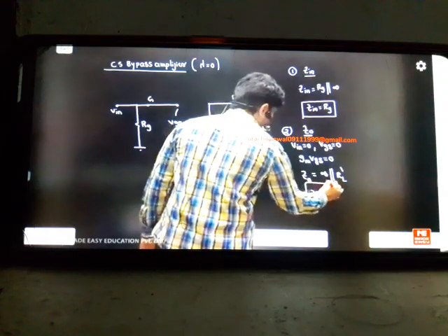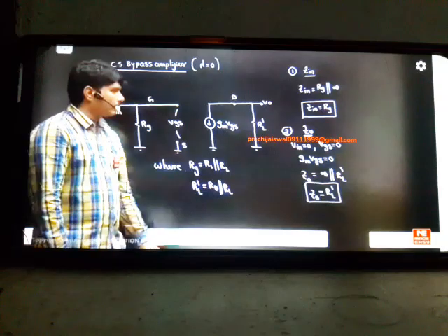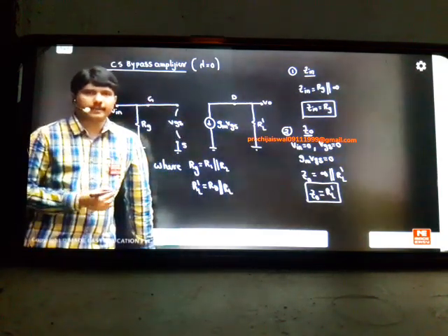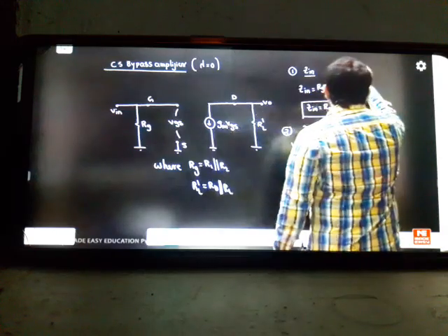So we expect the same answers for BJT classes and MOSFET classes. The only slight difference is that there it is RG parallel to r_pi, and here RG parallel to infinite. That is the difference we are getting. And coming to point number 3, voltage gain, if you want.